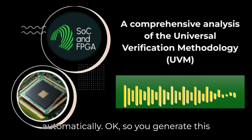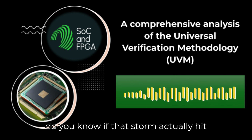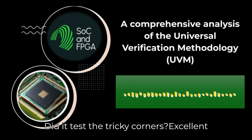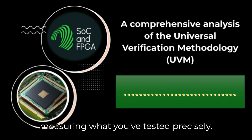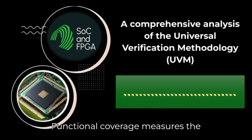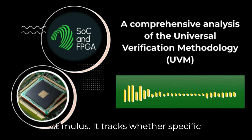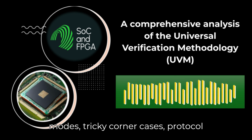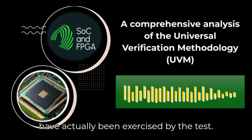Okay, so you generate this massive, smart storm of stimuli. How do you know if that storm actually hit all the important parts of your design? Did it test the tricky corners? Excellent question. That's where the second part comes in. Functional coverage. Measuring what you've tested. Precisely. Functional coverage measures the effectiveness of all that random stimulus. It tracks whether specific design features, critical operating modes, tricky corner cases, protocol rules, whatever you define as important, have actually been exercised by the test.